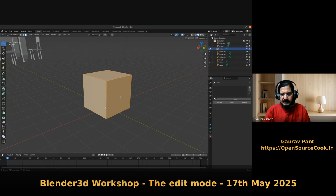I will show you. If I select this, there is this inset operation somewhere over here, you can select this. I prefer to use the keyboard shortcut, so I'm going to press I. Once you press I and move your mouse, you can create an inset face. Now, inset face has two aspects. If I select two faces and I press I, one inset is this.